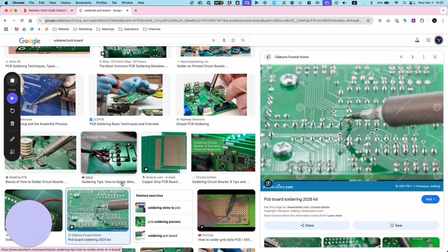It says 14.8 volts. You know it's 4 cells in series. So, knowing what we know about series circuits, what does that mean each cell is? 14.8 volts divided by 4 cells is what? 3.7. 3.7 volts per cell.